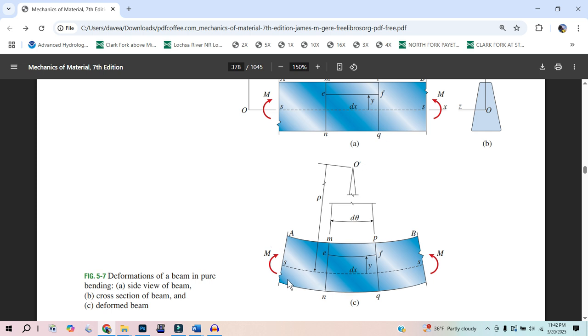Okay, so there's two different ways. Material mechanics is always like, hey, things can only lengthen so much, and that percentage is tiny. For steel, it's 0.2%, so it's good to rattle this number in your head of 0.002. So I'm going to hopefully go over this in just a couple sentences. If I have something that's a length of 1 meter or 1,000 millimeters, I can lengthen it to 1,002 millimeters. That can be its new length, and after that's the point where we consider it failed. I can also crunch it in to 998 millimeters. That's as much as I can crunch it in. That's going to be failed.